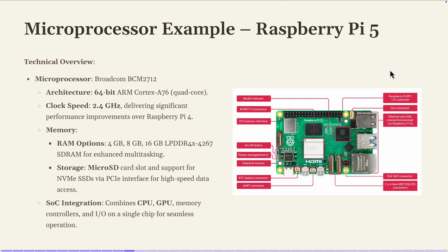For the Arduino, the processor understands in 0 or 1, digital? Yes, everything in processing must be digital. So why do we convert from analog to digital? Why not just directly convert from analog to 0? Digital is 0 and 1. This is what we call digital. So you have a continuous signal, which is analog, and there is an ADC that will convert it to a series of ones and zeros, what the machine would understand.